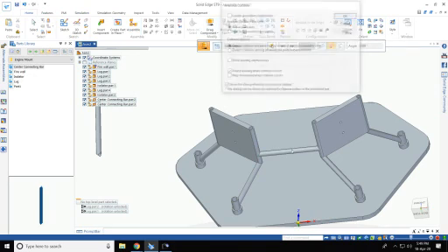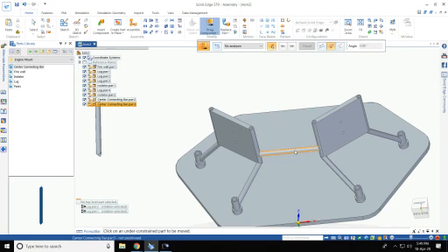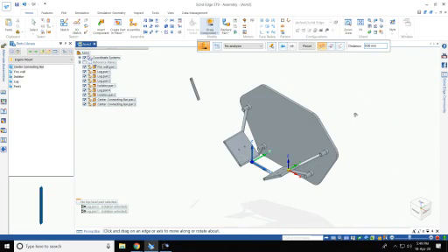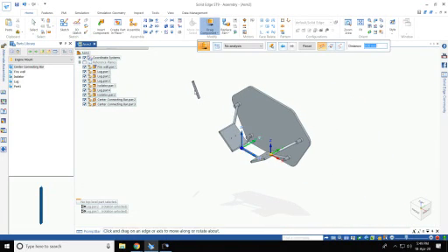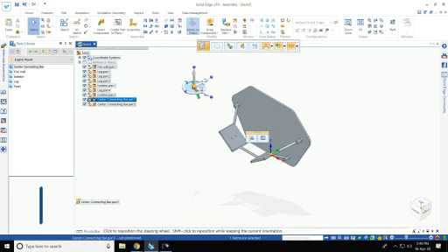Okay, now drag this component linear to your y direction and keep it somewhere in the middle, and done. Your assembly is done. There's an extra component, delete it. Select, delete.